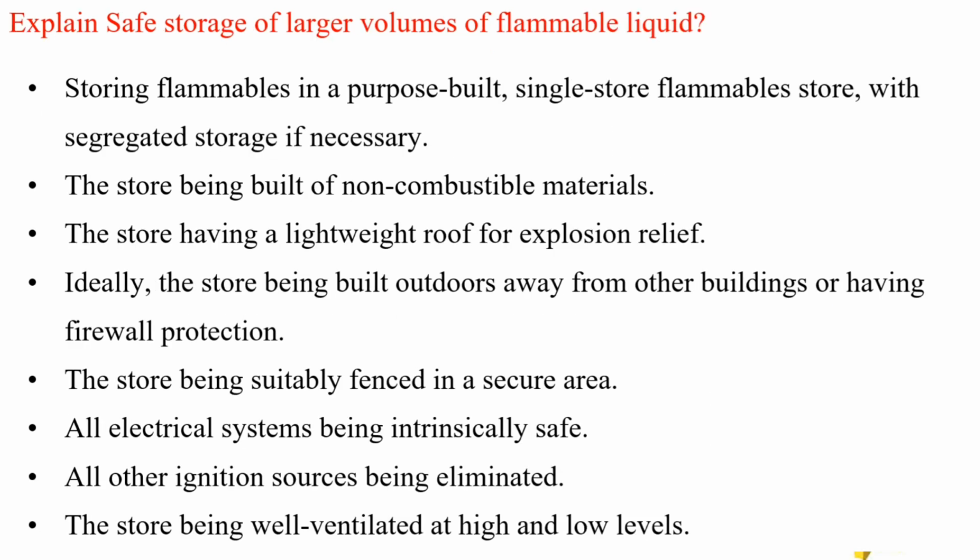Explain safe storage of larger volumes of flammable liquid. Storing flammables in a purpose-built, single-story flammables store, with segregated storage if necessary. The store being built of non-combustible materials. The store having a lightweight roof for explosion relief. Ideally, the store being built outdoors away from other buildings or having firewall protection. The store being suitably fenced in a secure area.